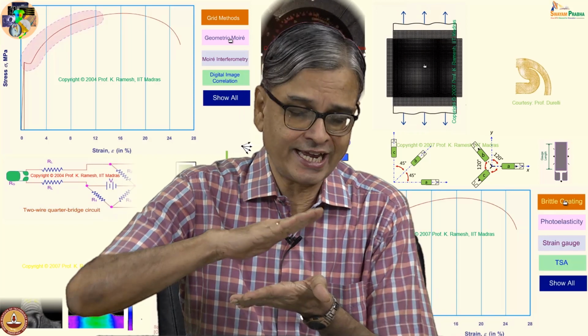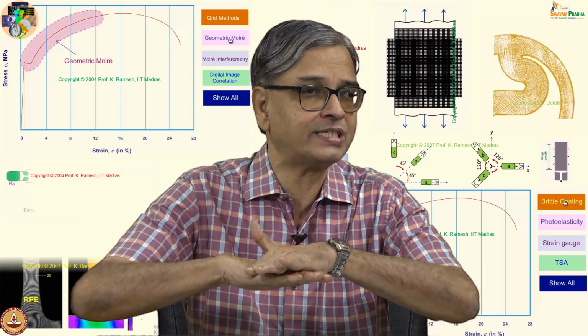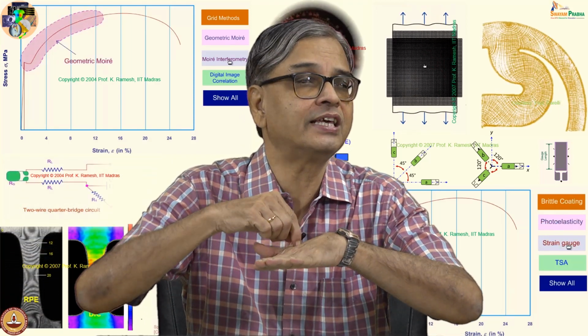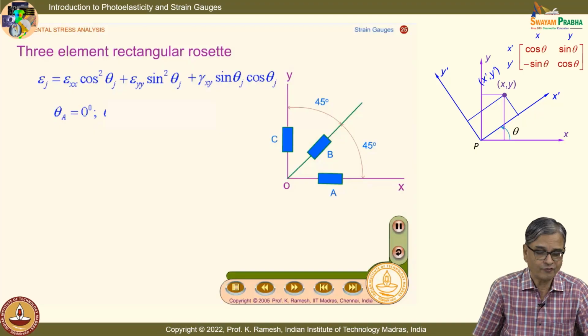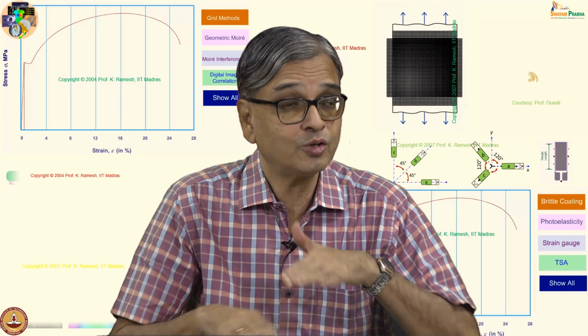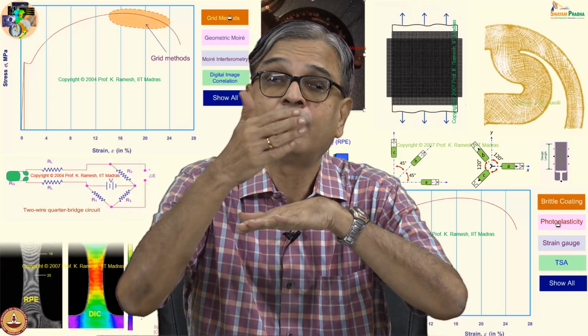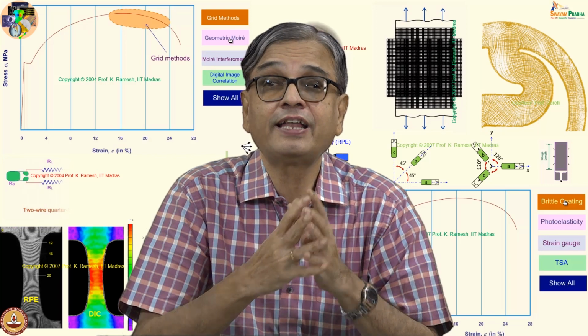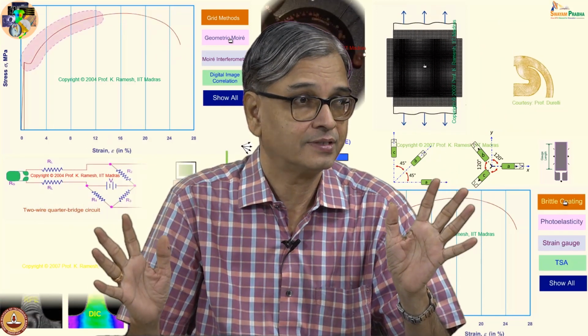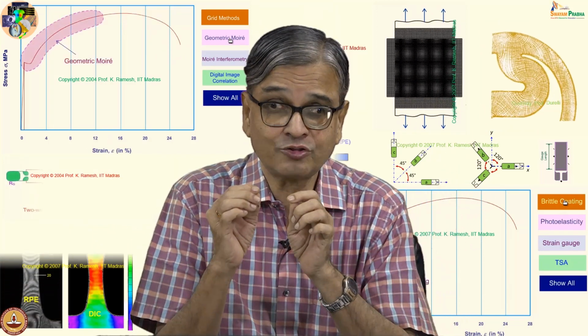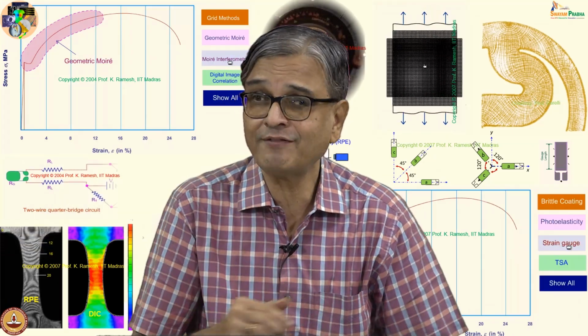You also have strain gauges where they are stacked one over the other, so that the center of the strain gauge forms at this point, but you amplify heat generation 3 times. So, you should have a very positive way of taking away the heat. So, your measurement should be sensitive to that. You may not have the luxury.